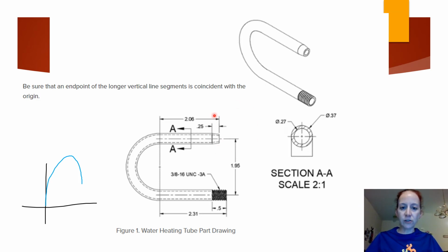The other way I've constructed the tapered end is by doing an offset plane from the end of the pipe and offsetting it by 0.25 inches. You can see the dimension there. And then doing another circle of smaller dimension and then lofting from the end of the pipe to the circle. The problem was, if you do watch the catastrophic water pipe video, is that Fusion would not loft it for me, and I'm not sure why, because I have successfully gotten that to work in the past. So we'll see how that goes.